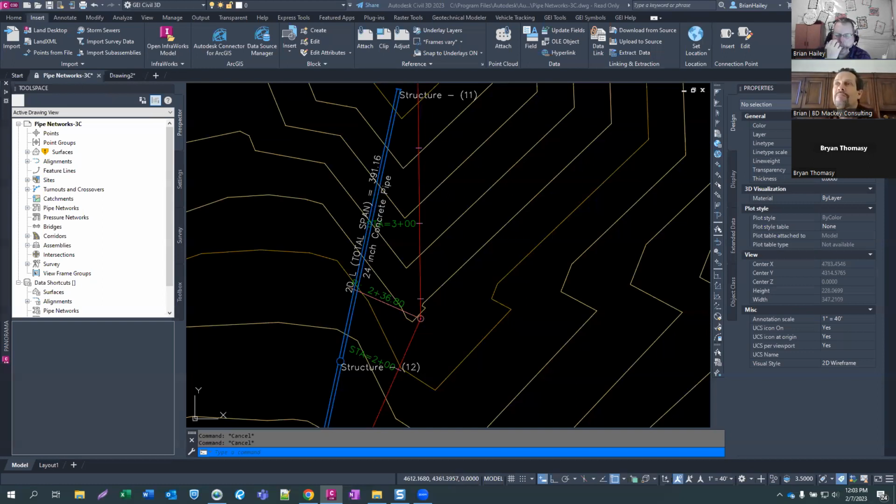Yeah, no, and I always say it's the exact same way, because I didn't know that was ever a problem. Granted, I'm not the average Revit user. I like to think about other people, not just, screw it, I'm giving you some export because you told me to. So I like to try to set those things up. Knowing that that can happen, I'll have to start looking at some of my AutoCAD exports. The big thing I always tell people too, and this depends on the firms and teams you're working with, is I always set up every single project to match civil coordinates.